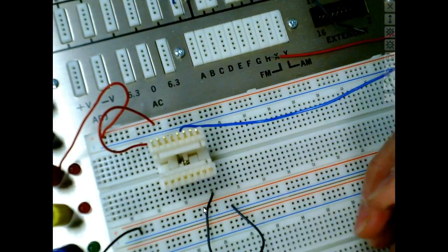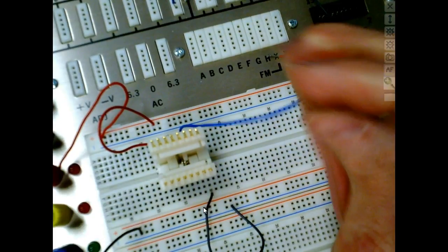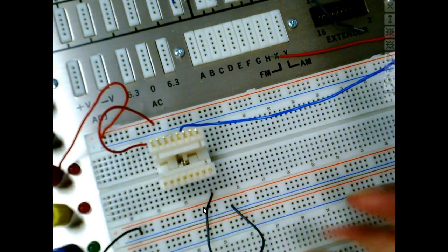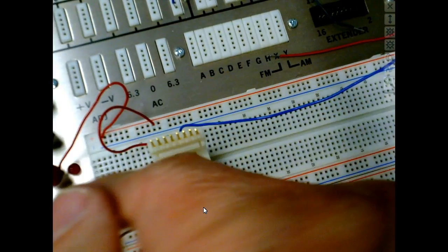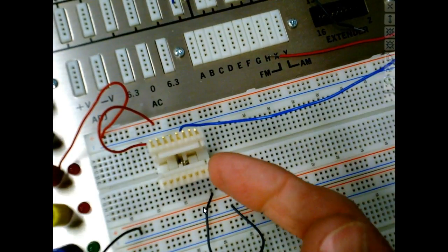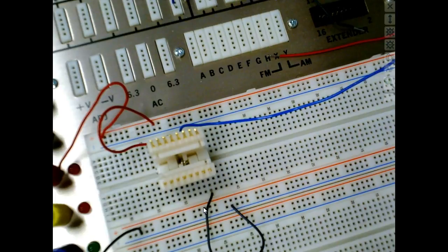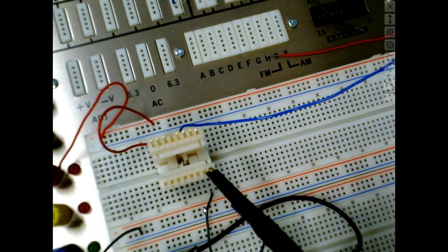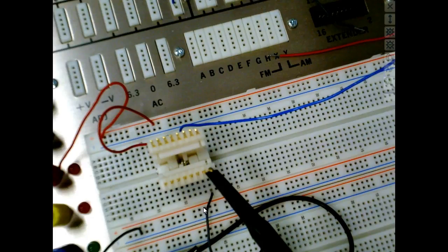They're not very expensive. Y'all see that? Ain't that neat? Now if I've got a logic analyzer, I can come up here and hook up all these pins without trying to get into the chip itself. And if I'm using a scope, you don't try to push it in like that. What you do is you come in on the side, put it vertical, and then you roll it over. Now you can latch the scope onto that thing and just leave it there, which is pretty neat. So these are chip clips. You can buy them in just about all shapes for all the chips you got out there, all the DIPs.